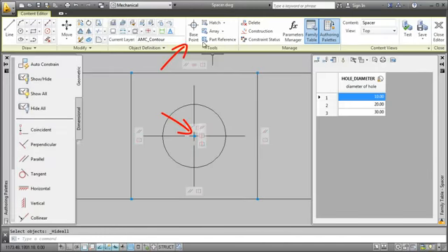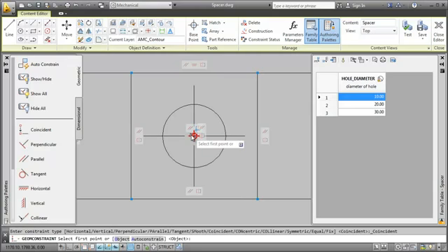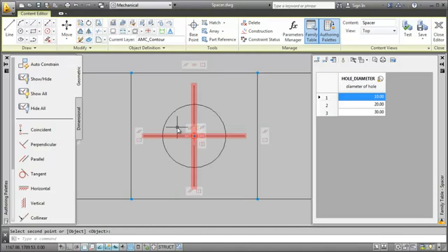Moving on, I define an insertion point for the spacer, and then I constrain it so it won't move when I resize the part. I must also ensure that these center lines get created on the correct layer. So, I move them to the layer assigned to center lines.